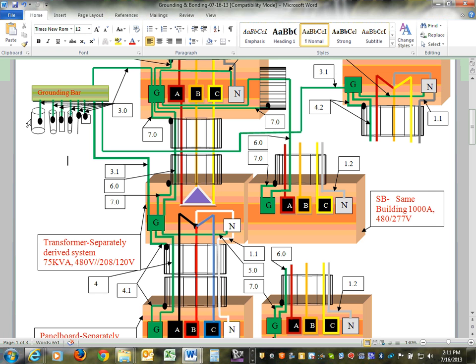Yeah. And I always wonder, Dave and everybody else, if you bond the gas pipe at the top, well, how about the bottom? That's what's coming underground. I believe they have insulation inside the meter somehow, because if it's all metallic and you bring an equipment bonding jumper to the gas line above the ground, the gas line under the ground, which you're prohibited from using, they're tied together through their meter, but I think they have insulation somehow in the meter. But it never bothered me to do it. It's underground. Yeah, they don't want you to tie to the underground.